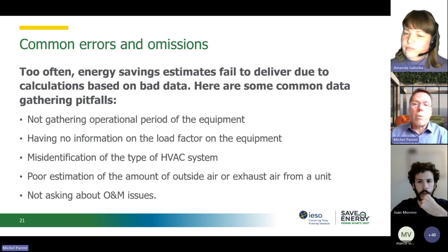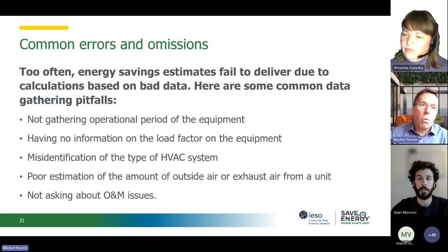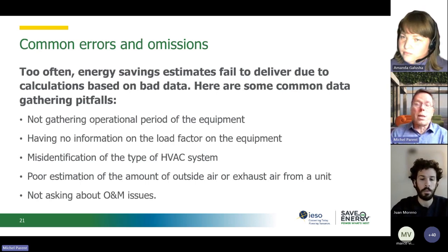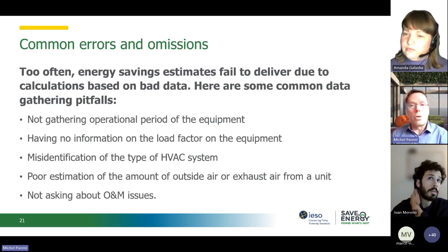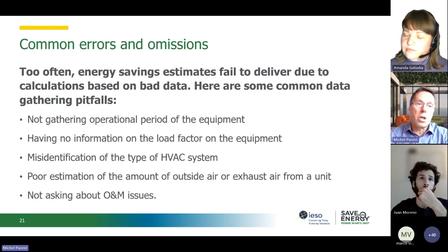So never carry over the nominal efficiency directly to RETScreen without doing a correction downward to account for the purge cycle, any kind of short cycling that would really reduce your annual efficiency. Everything in RETScreen is always based on annual efficiency.